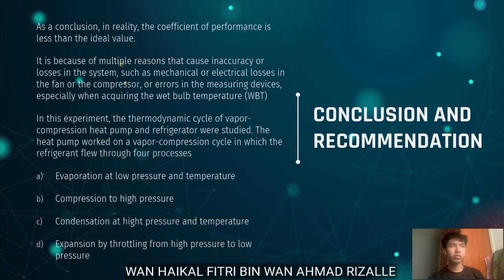And the last one is the conclusion and recommendation. As a conclusion, in reality, the coefficient of performance is less than the ideal value. It is because of multiple reasons that cause inaccuracy or losses in the system, such as mechanical or electrical losses in the fan or the compressor, or errors in the measuring devices, especially when measuring the wet bulb temperature, WBT.